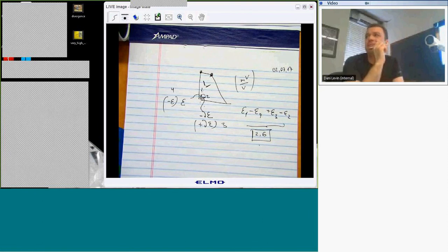It's just that he's cleverly chosen the location for the bending mode to give you mostly bending, and probably primarily first bending, and then he's chosen a clever location for the torsion mode to primarily emphasize first torsion. But you'll see other responses.